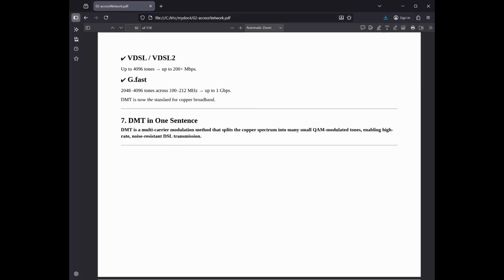Feature, function, benefit. Subchannelization divides the spectrum into 4.3125 kHz bins, which prevents total signal loss from localized noise. Bit loading assigns bits based on SNR per bin, which achieves the theoretical maximum speed of the wire. Bit swapping moves bits between bins during operation, which increases connection stability. The cyclic prefix adds a time buffer between symbols, which eliminates errors caused by signal echoes, multipath.